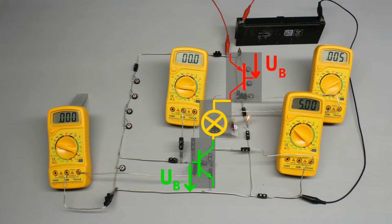pin. To limit the current running through the voltage divider, a filament lamp is connected in series to the transistors. The functionality of the second filament lamp will be treated in the video about adjustable voltage sources. 4 digital multimeters are used to measure the voltage drop and the current at the base and the collector pin of the NPN transistor. As we saw in the first series of measurements, even a current below 1 microampere affects the electrical properties of the transistor clearly.